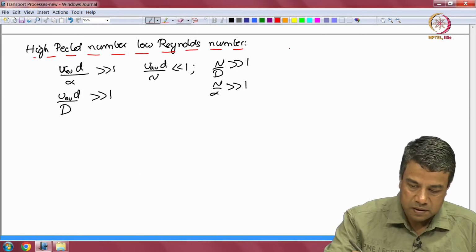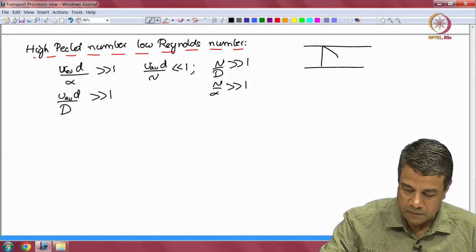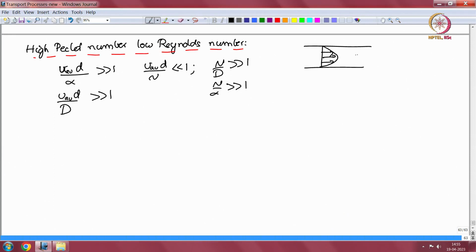So, for one particular Reynolds number, if I have a parabolic profile, and I increase the Reynolds number, the maximum velocity will increase. However, if I divide the velocity by its maximum value, then I will get the same universal parabolic profile for both of these cases. That means that the velocity profile is a linear function of the driving force. It is a linear function of the pressure gradient.